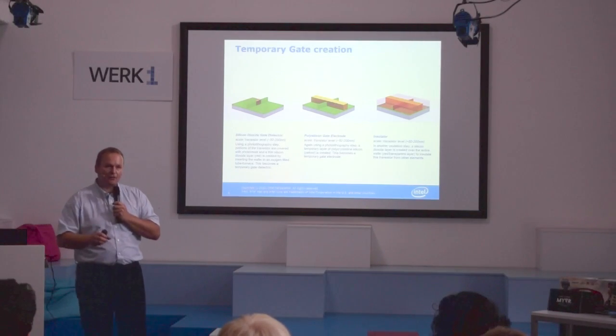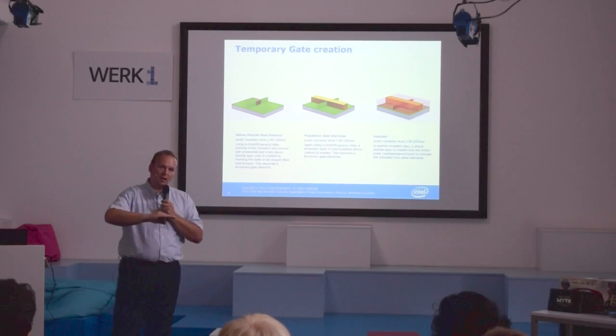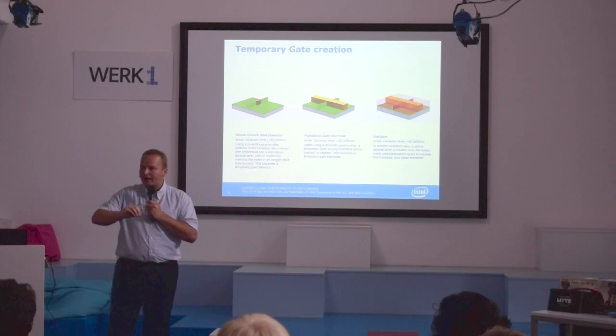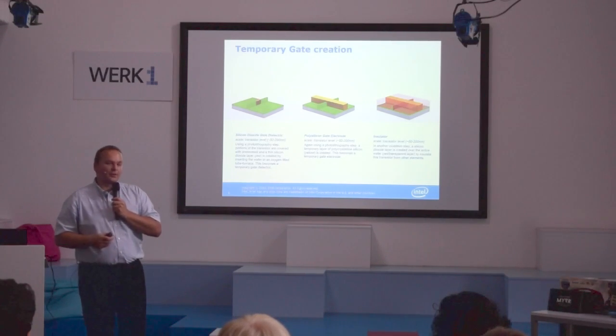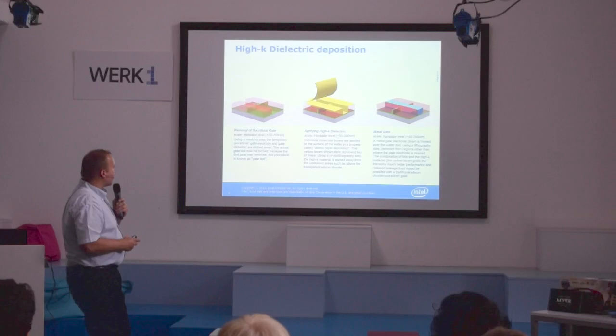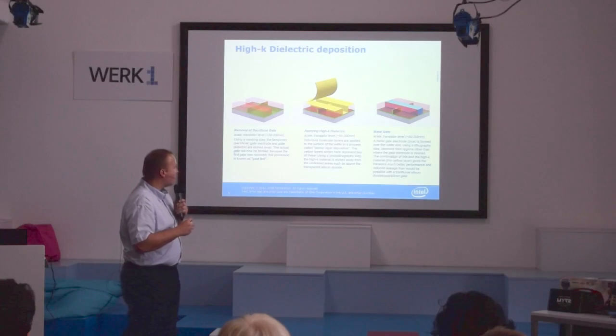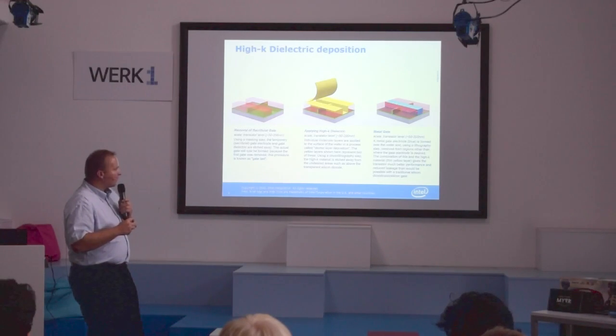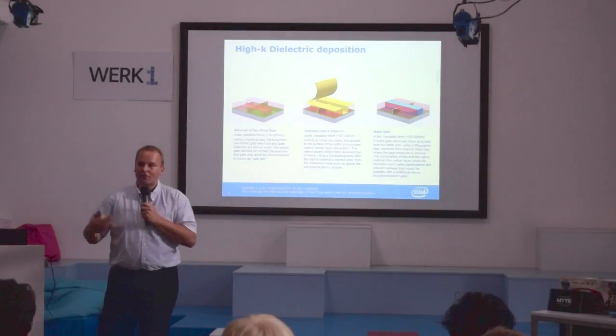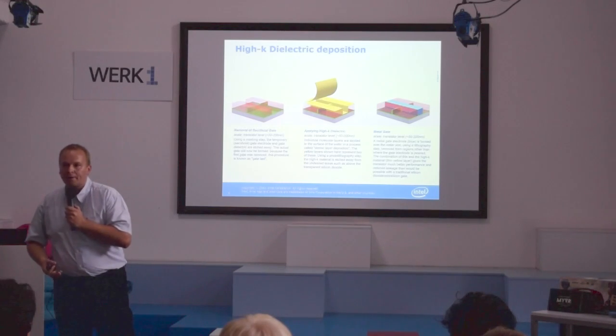And the transistor level really is the very bottom level of that wafer, the first layer where the transistors sit. And then there are more steps applied where we put in, for example, a high-K gate dielectric, and there's also a metal gate applied in order to make this transistor switch the way we want it.